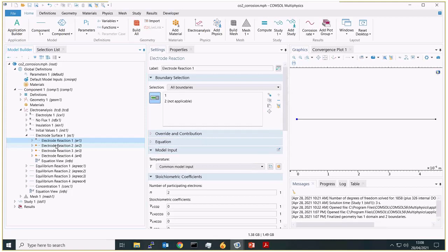So mainly asking about sour corrosion. Is it possible to add H2S impact in the CO2 corrosion? I think that's probably something we'd have to look into in a bit more detail. At the moment it's probably only sweet corrosion, only with CO2, not having the impact of sour corrosion and H2S. Possibly, yeah. Okay.